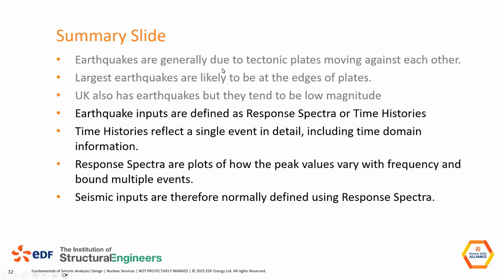Okay, so my summary of where we've got to now. So we know what earthquakes are. We know about why they occur, and in the UK we're generally safe. The new information, we've got spectra or time histories. Time history is a single event in a lot of detail and includes the variation with time. Response spectrum is a plot of the peak response varying with frequency, and it's an infinite number of events. And because of that, we normally use response spectra as our base input and then derive time histories to match them.